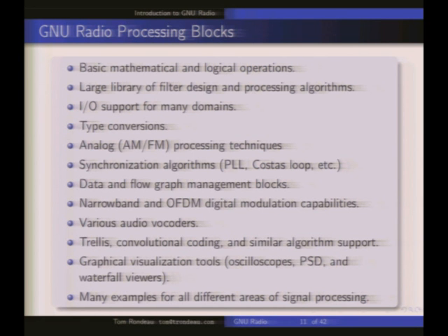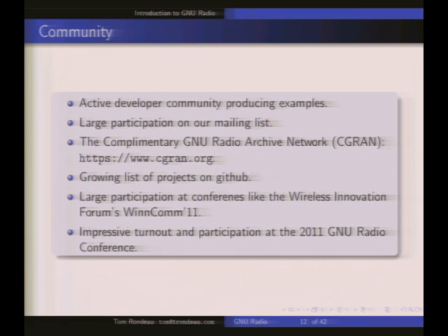But once it's locked on for a while... if you then break that communication and just start introducing noise, your carrier recovery loops go crazy, and then they have to go from scratch to relock the next time the bursty packet comes in. It's not the right way of doing things, and the last couple of slides of my talk will reintroduce this concept and what we're hoping to use to solve the problem.